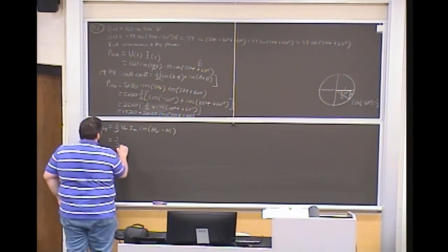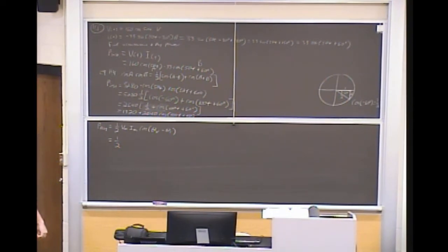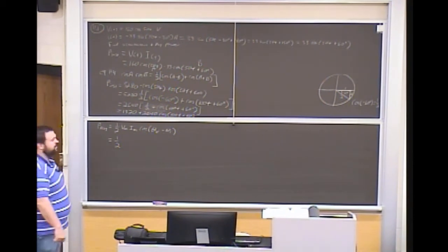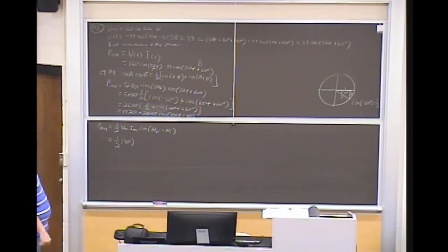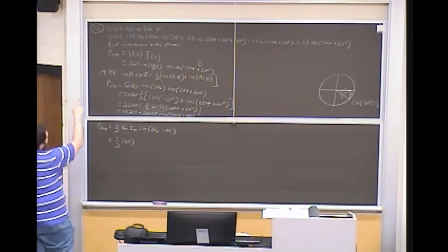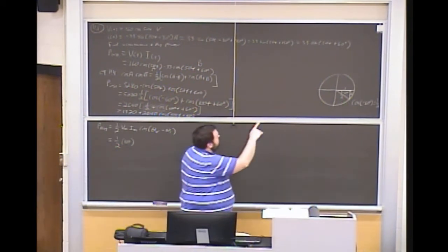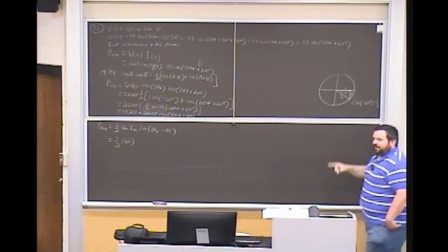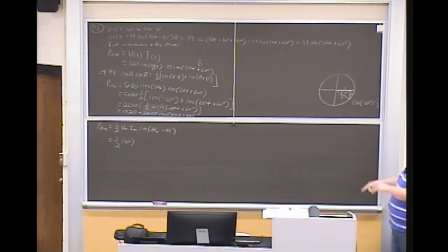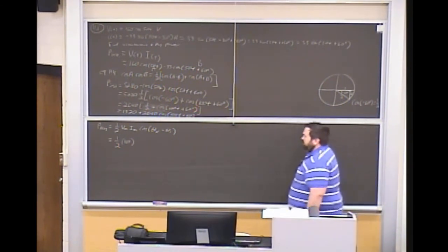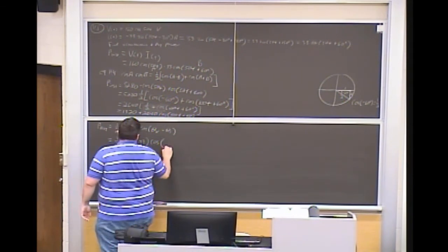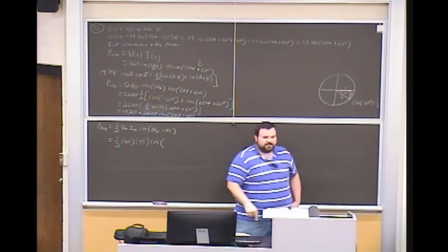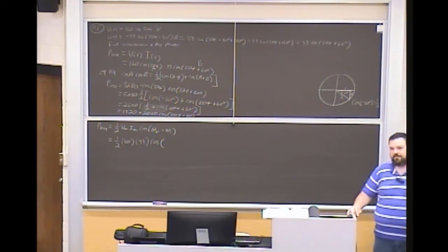We know 1/2. What's our Vm? Comes from the V of t. 160, yep. What's our Im? Now, if I go back to the initial I could say negative 33, but if I want to use this as my theta I, because it's now in cosine form, I'm going to use just 33 right here. And then that way, with my cosine, now all my thetas are relative to cosine functions with positive amplitudes.